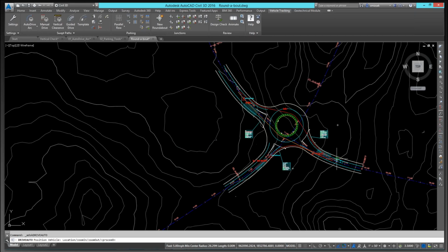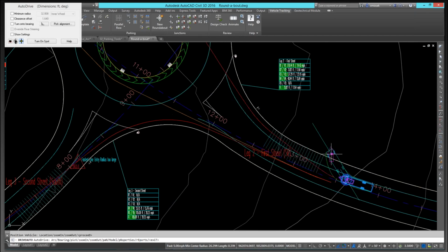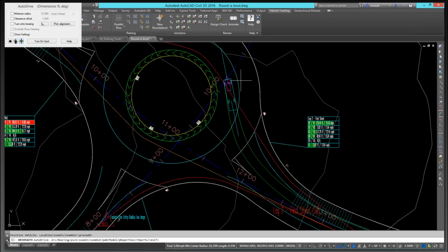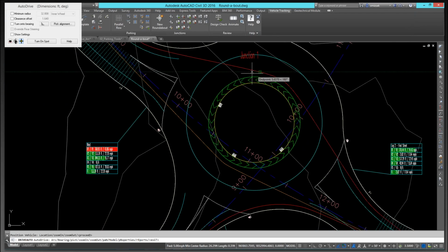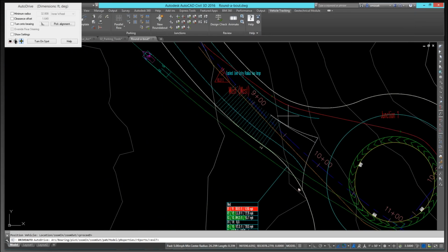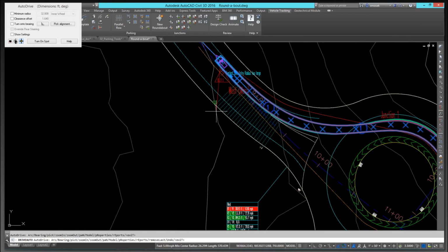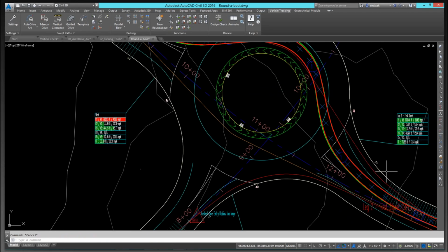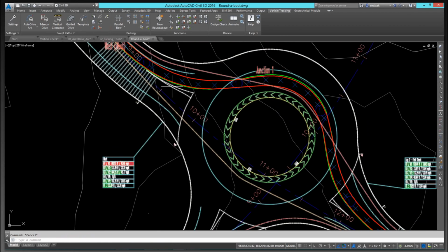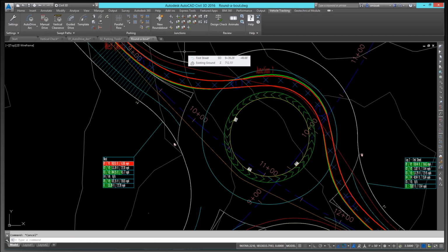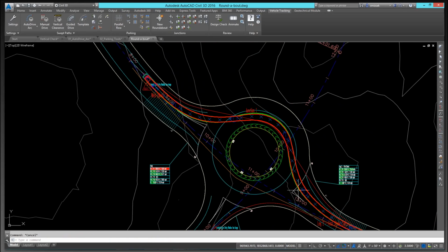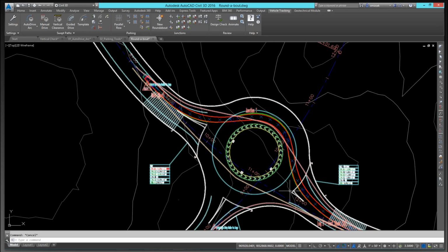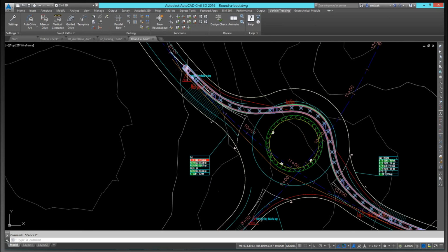Say okay, and when I drop it in there, it already recognizes it as a lane, so I can then come in and say, yep, go to there. And that quickly, I can see that my garbage truck should have no problem getting through that roundabout. Now a 62-foot semi, hey, it might have a little bit of issue getting through that roundabout. With the horizontal swept path, it automatically knew which way I wanted to go.